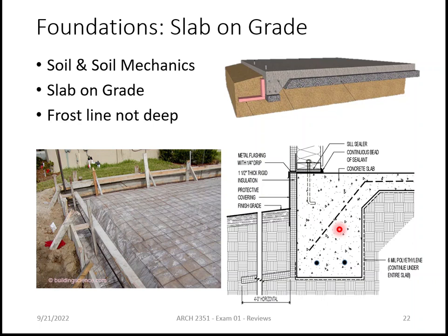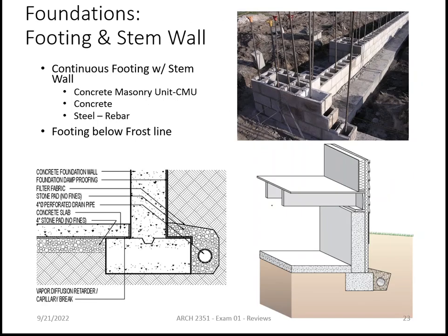Sure. There's the footing and there's the slab. Those are the two primary ones, made of concrete. Then there's wire mesh that goes in the slab. That's the steel that gives it some tensile strength. Then there's rebar that goes into the footing, which gives it tensile strength. And then there is usually some waterproofing material, polyethylene or something, used on the ground to keep moisture from being absorbed into the concrete. So there are five different components.